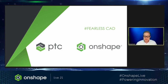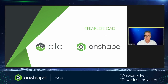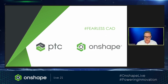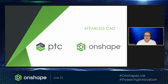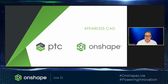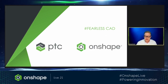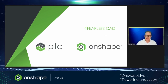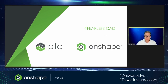We generate a large number of document drawings which have a standardized number and arrangement of views as well as standard general notes. Is there a way to quickly accomplish creation of drawings with Onshape? Now, making a drawing template, that's what you want to do. And it's pretty easy. You can apply it every time you start a new drawing, or you can go back and replace the ones that were there before. So in addition to those things you talked about there, I think orthographic views, standard general notes, dimension styles, text styles, projection types, all of those types of things can be captured in this template and very, very quickly reused.